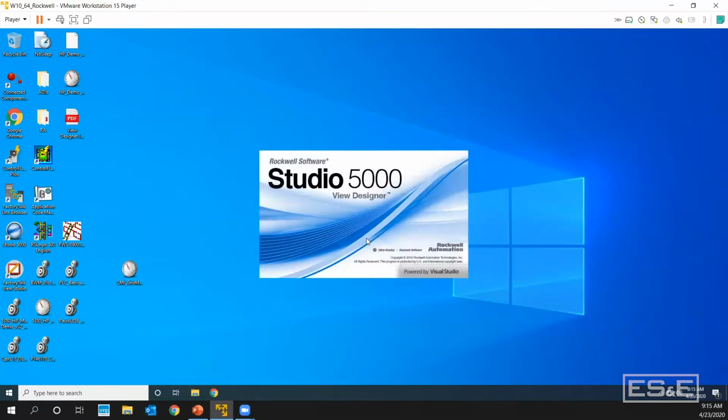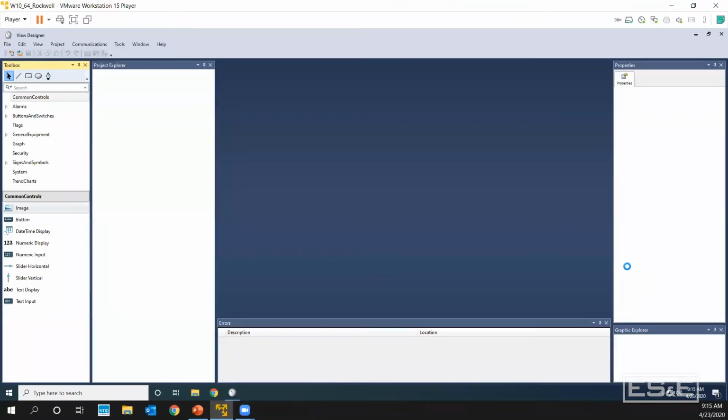This takes just a few seconds to get set up, but once the project finishes creating here, it will then open up and it will default to the configuration screen in which you need to configure the PLC path and the PLC file. So the PLC file is required because that is how the software sets up your tag database.